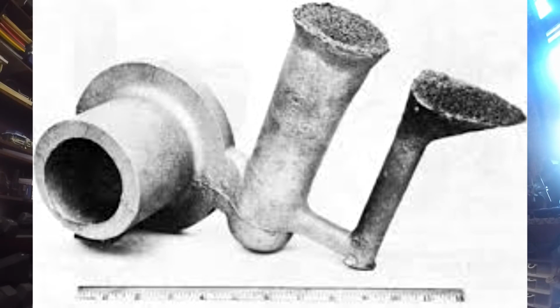They should have had something like that at the bottom of the sprue, so that whatever amount of dross they manufactured when they poured down that sprue would have been mitigated by that splash basin, and less dross would have been fed.